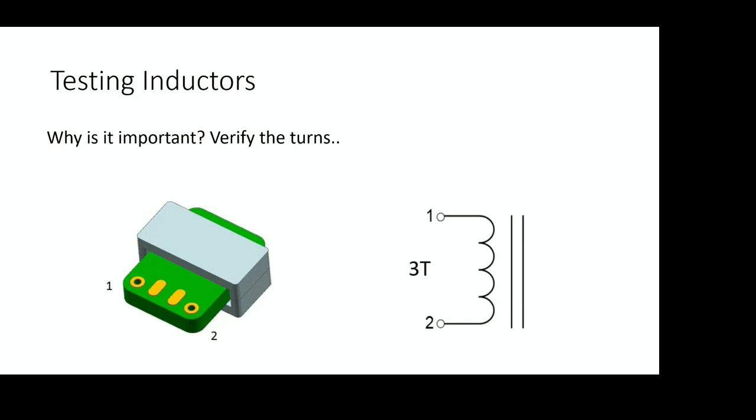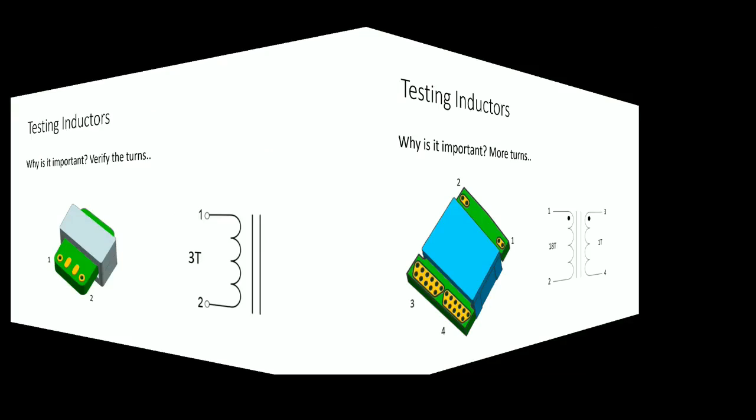And so you can see some of this sometimes now, even in a PCB, if they have a transmission line or something in a PCB that needs to be a certain length, but the PCB is maybe only 3 inches or 4 inches long, they can do something like this example that we have here on the screen now, where you just have a primary, but you have a certain amount of turns, and that allows that transmission line to get longer, even based on your short amount of space.